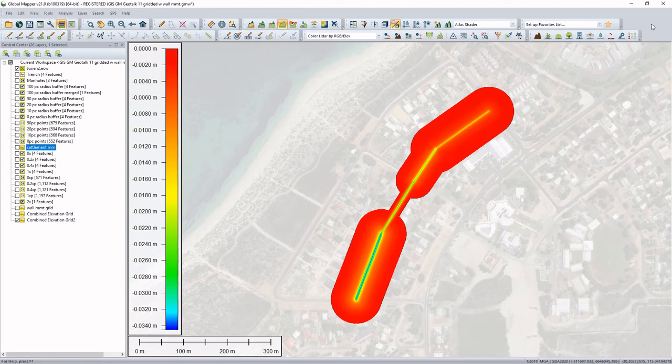Now I've got my final grid, I can contour it to see what the effects are on the surrounding structures. There are two types of settlement that I'm interested in. Total settlement, that is a total vertical movement from pre-construction to post-construction, and differential settlement, which is the slope of the settlements. So buildings are particularly susceptible to differential settlement.